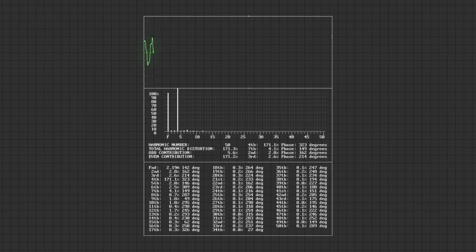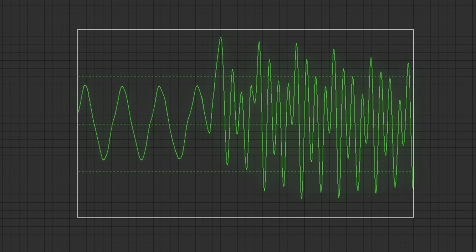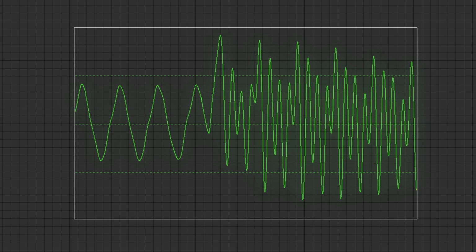Well, after we settled in and performed some measurements, what we found was a harmonic resonance problem created by a poorly designed harmonic filter. Instead of reducing the harmonics, the filter actually amplified the harmonic currents and created a 5,000 amp pulse of current through a large inductor on the platform. The sound was a consistent thump, thump, thump, which resonated throughout the platform. That was the bad noise.